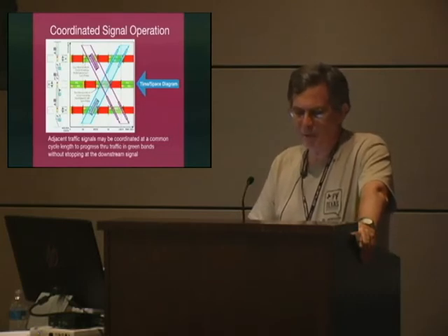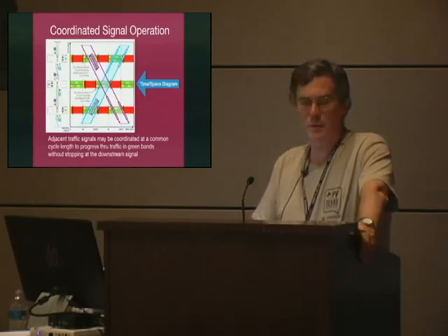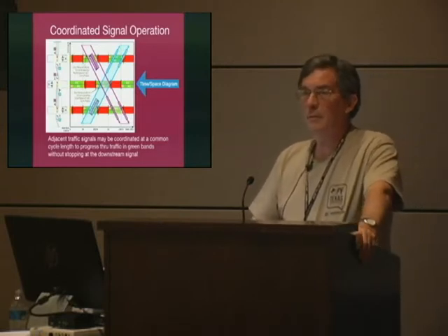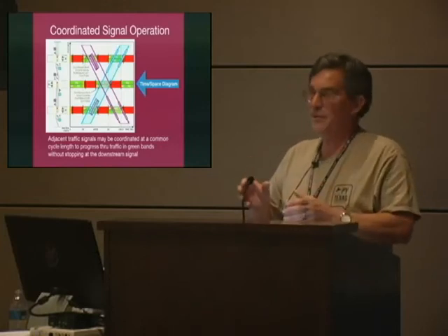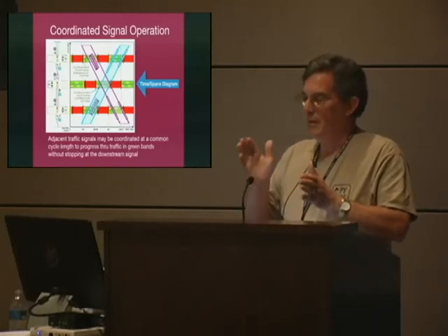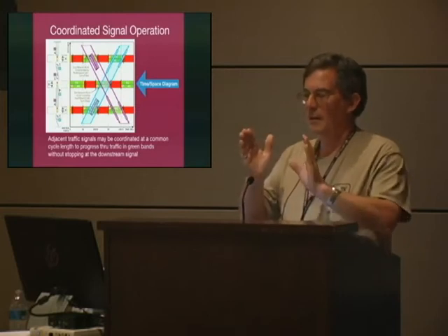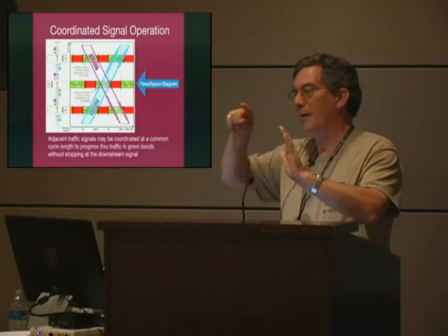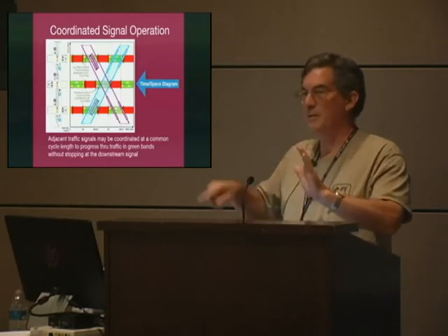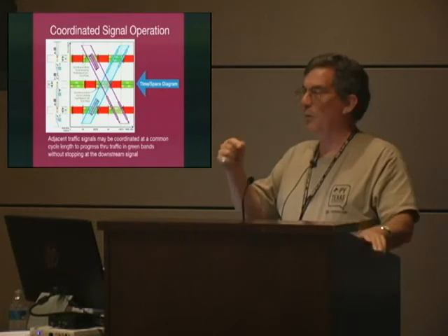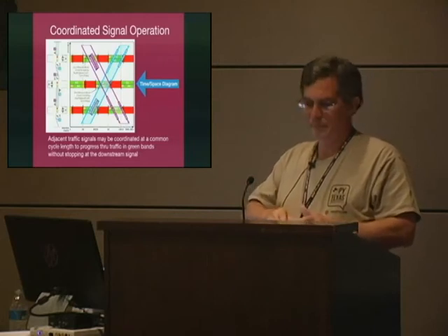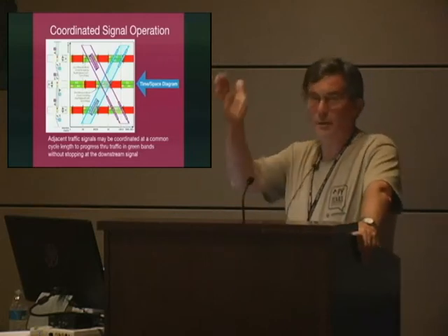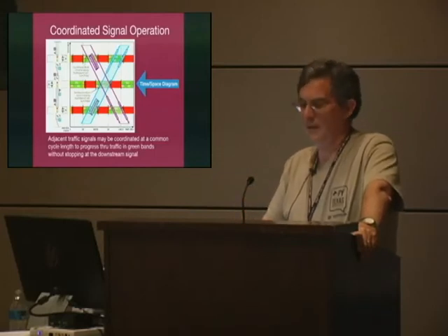And we have something that we deal with called coordination. Right before lunch, we had a good talk on POSIX time, modules, and the way the lights are synchronized is that every traffic signal controller is synced to midnight at the same point. And so that cycle counter at each intersection is synchronized to midnight. And there's a sync point within that cycle that allows you to have a coordinated movement if every traffic signal along your arterial is timing the same cycle length.